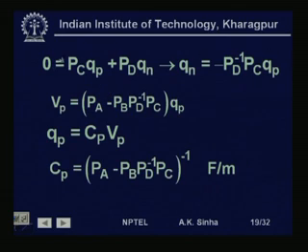Now, what we have done by doing all this is we have eliminated the effect of the ground conductors, that is the ground currents which were flowing; that effect is included by modifying the phase conductor capacitances.